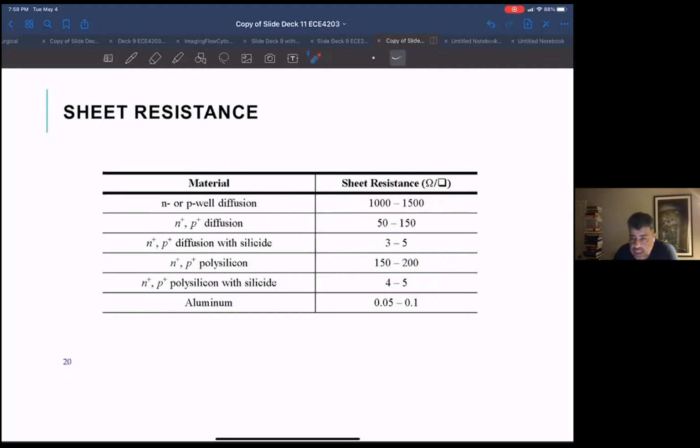There are extraction tools that feed back these values to you, but they tend to be time consuming to run, so some people take shortcuts while doing extraction. All your tools may tell you you're okay in simulation or verification, that point A is connected to point B, but the problem is it might be connected with a very, very high resistance and may be running nowhere close to the speed that you need.